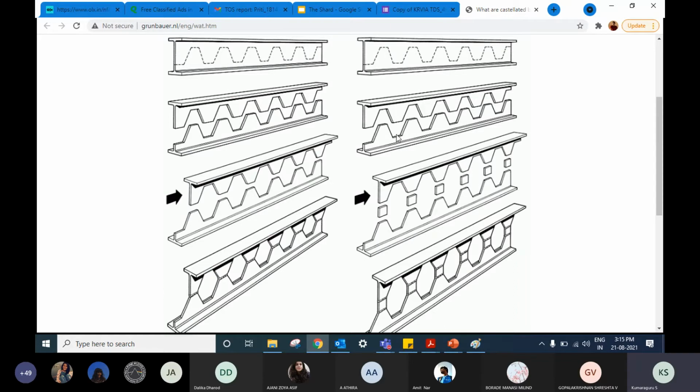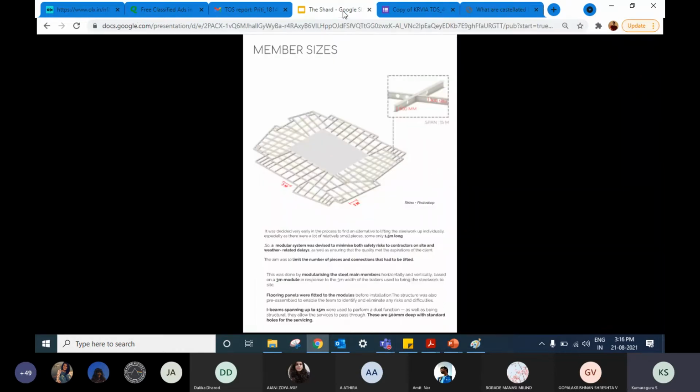So here, look at this example. They want to increase the structural depth much more. So they added some square or rectangular plate members in between the two cut members, and they then welded everything together. Okay, so here, when they're having a 500 mm depth or 300 mm depth, it's already available. What they're doing essentially is making web penetrations, right?